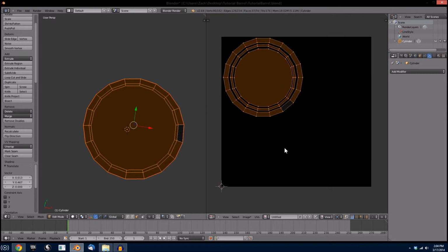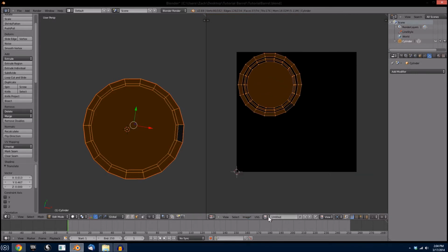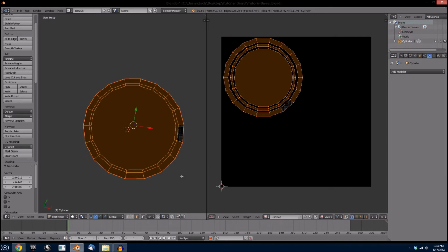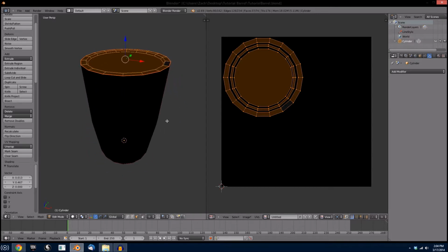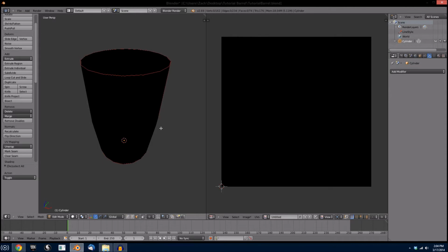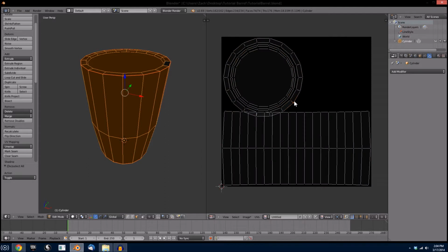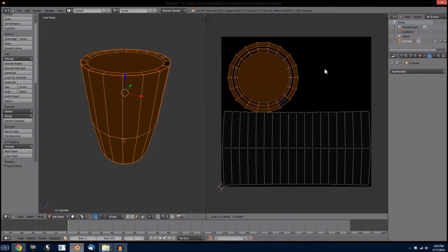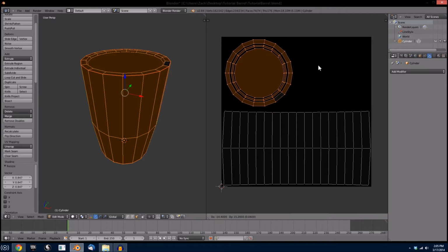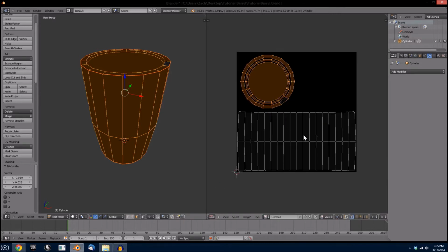make sure that your image is selected here so that everything displays on the same image in the same material. But to see these vertices we unwrapped previously, we just tap A twice. And as you can see, we've got some overlapping that we need to take care of. So just holding Shift, select these three vertices, one of each individual unit. Use the Select More key and scale this down and pan it until no vertices overlap.